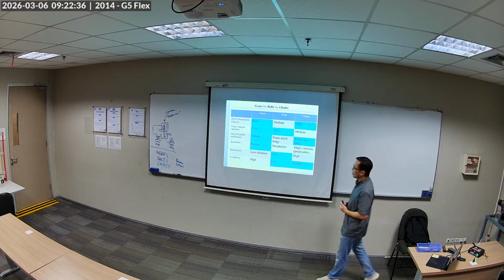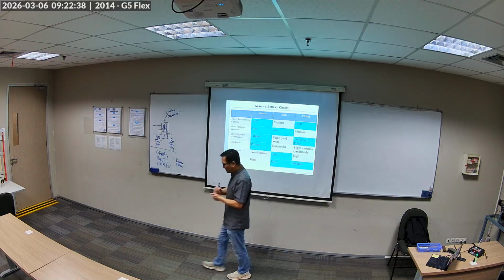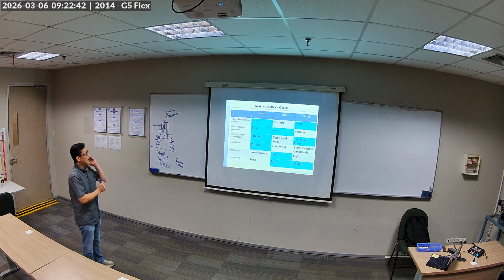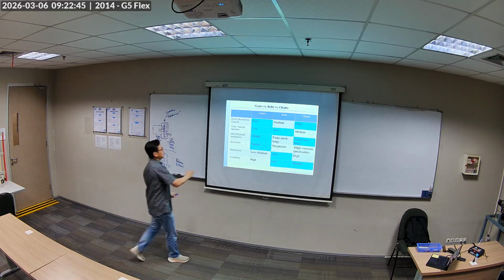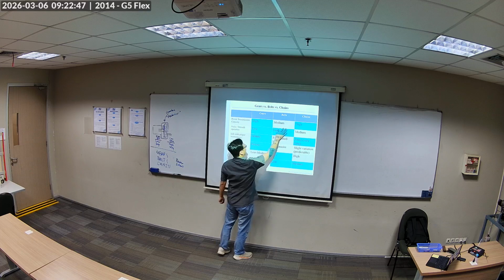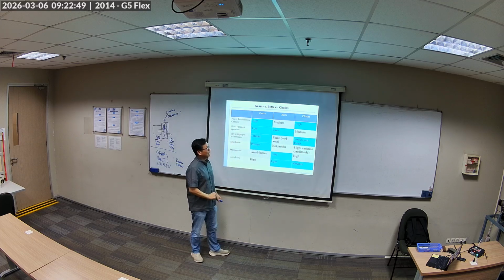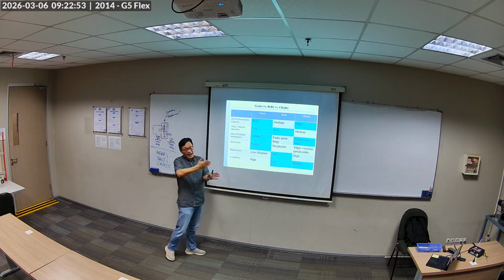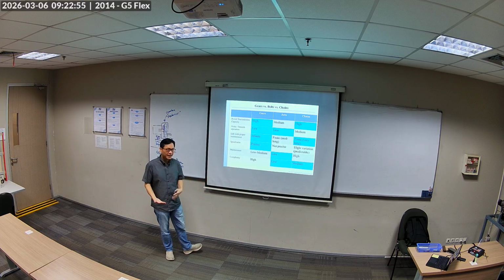This is a quick comparison of gears, belts, and chains. This is kind of an overview before we get into gears. We have capacity, okay? Gears have high capacity, belts medium. You can add the number of belts to get higher capacity, but not real high.